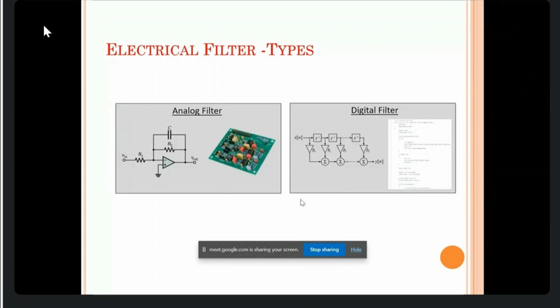So in the transfer function, particularly if we take a simple low pass filter, series resistor, shunt capacitor, in that low pass filter you'll find the transfer function, voltage applied in and voltage out, based on the Laplace transformation. The Laplace transformation means we are converting to the frequency domain, the natural frequency domain, which has some real term plus frequency term, that is s is sigma plus j omega.